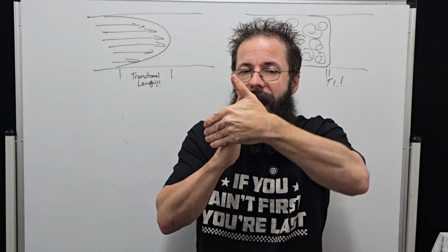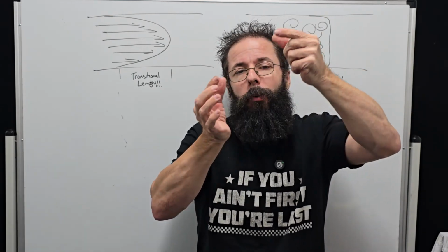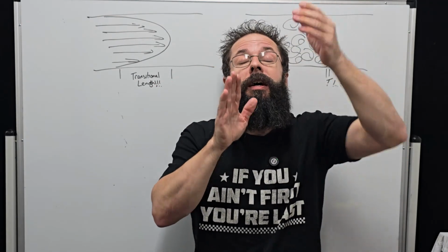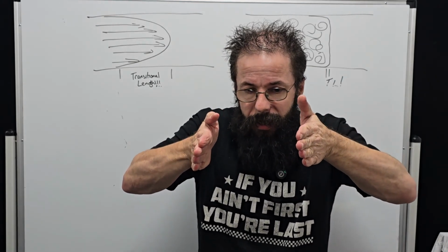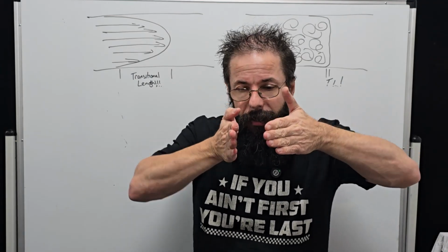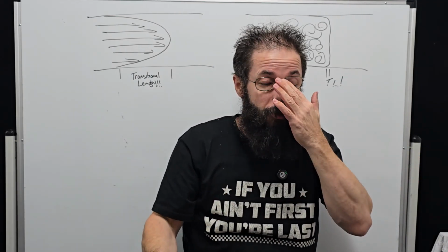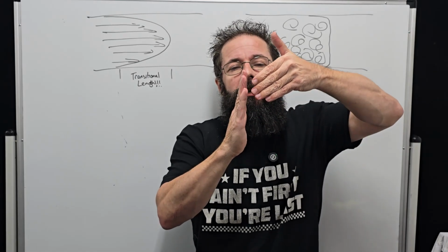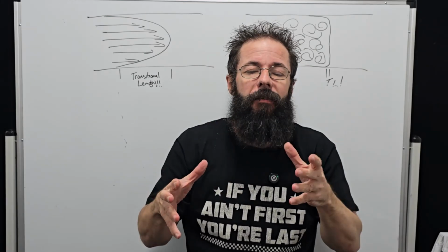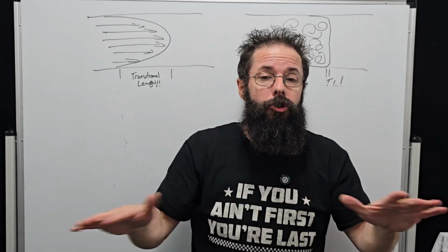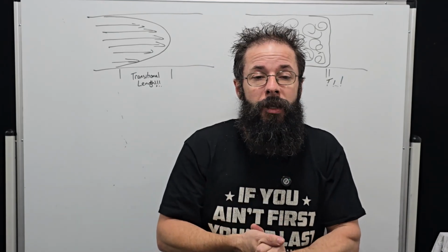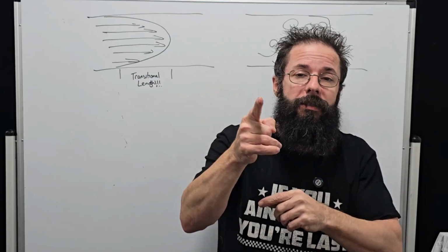It's shearing around it. And then if we're really, really smart and we put a nice shark fin separator in there, a directional shark fin, which will help separate the air, then rather than it coming around and colliding in each other, it meets that fin and guides into the port, or into the cylinder, I should say. So again, as we increase the port angle, it reduces how much shear stress that valve itself is going to create, and we reduce and almost eliminate any turbulence on the backside of the stem. So all right, let's go into the next part.